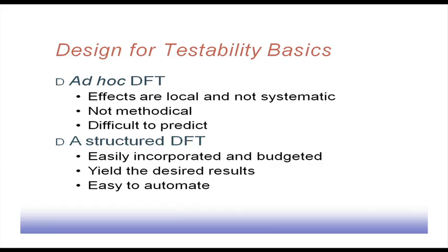On the other hand, if we have structured DFT, then along with the design itself, we incorporate this testability hardware, and it is budgeted at that point. It is the extra for extra testability. So, I will need this much extra logic gates, this much flip flops, or this much area. That is put into the budget itself.